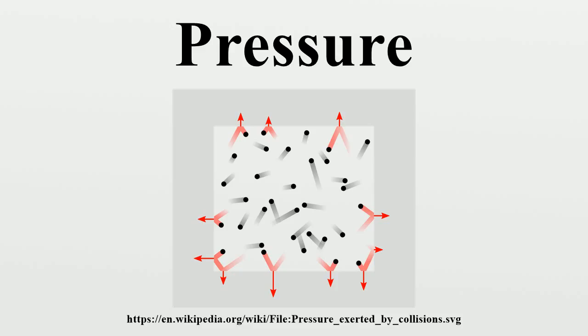Pressure is sometimes expressed in grams-force or kilograms-force per square centimeter and the like without properly identifying the force units, but using the names kilogram, gram, kilogram-force, or gram-force as units of force is expressly forbidden in SI. The technical atmosphere is 1 kilogram-force per square centimeter. Since a system under pressure has potential to perform work on its surroundings, pressure is a measure of potential energy stored per unit volume.